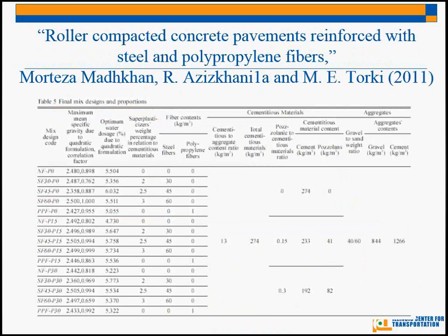In addition, people have also looked at using fibers with RCC, which is another important thing because typically with roller compacted concrete, you don't have dowels for load transfer, and you're not going to use reinforcing steel. And that's mainly because you have this really dense material that if you put it with the steel, it's not going to stay in place and work the way you want it to work. And so typically there is no reinforcement with RCC, which adding fibers can help keep some of those cracks that are going to naturally occur with concrete. It's going to help keep those tighter and make sure that they don't erode the pavement more so.